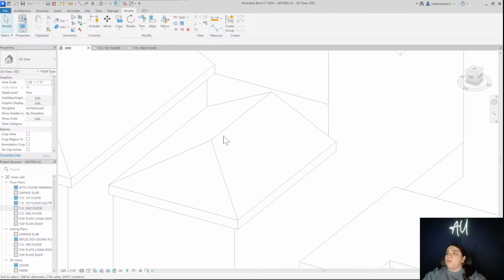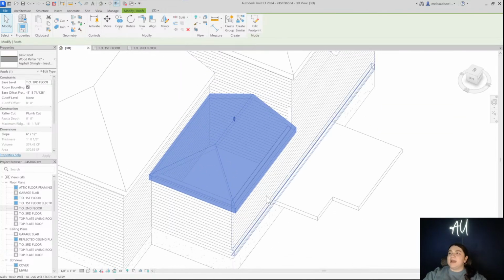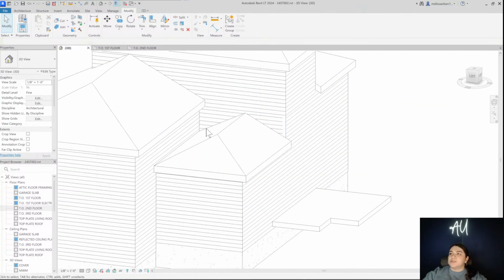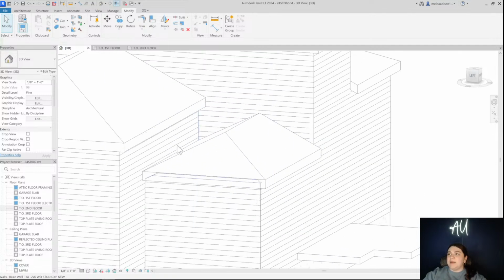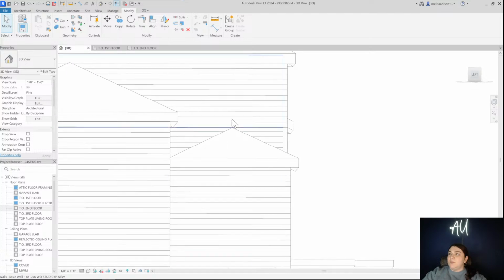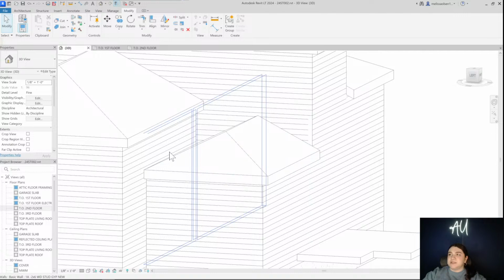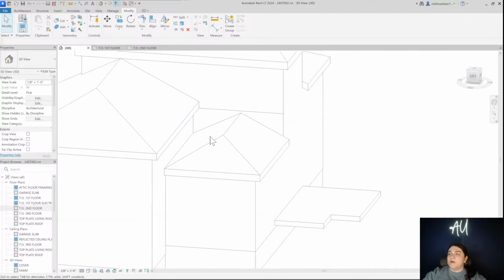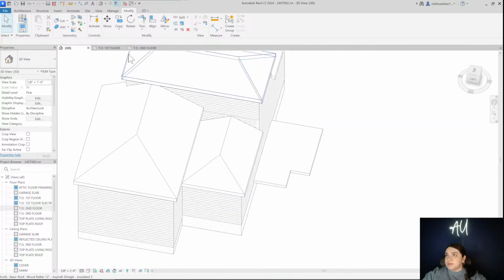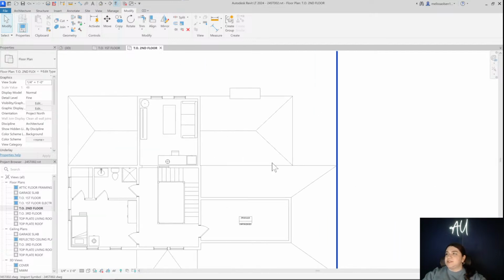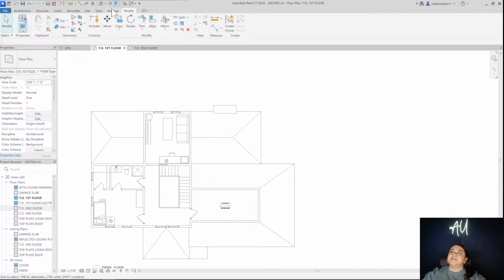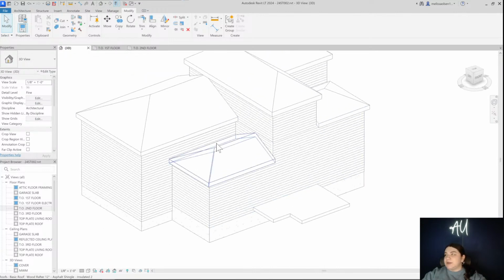So we want to fix this roof because you never want to have water from a roof or snow. I live in the New England area of the United States. You don't want snow to pile up in the corner here. And so if we leave the roof like this, it's going to cause massive issues and snow buildup along this side of the wall. So that's one of the things that, you know, Emily's just designing the floor plan. She's kind of just sketching out quick roofs, and then I go in and really bring it to life in the exterior.